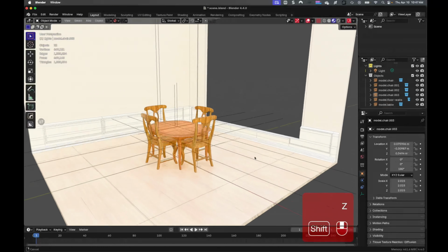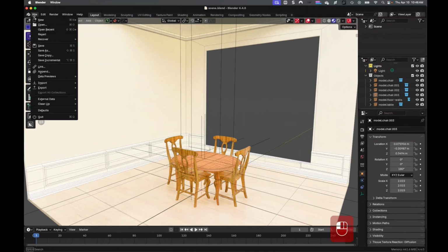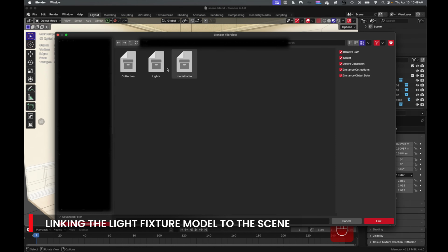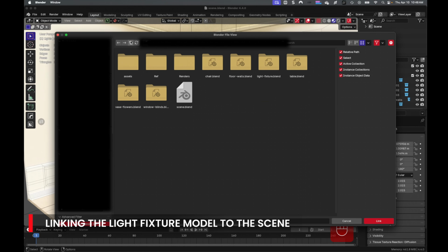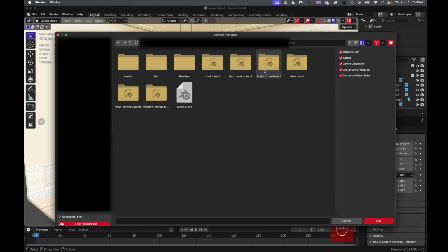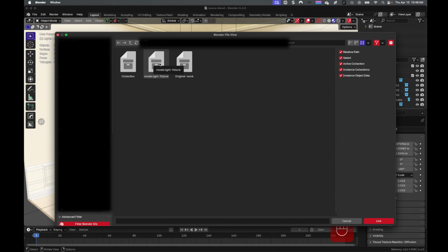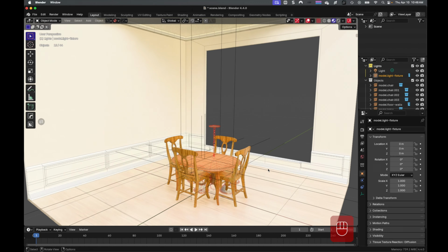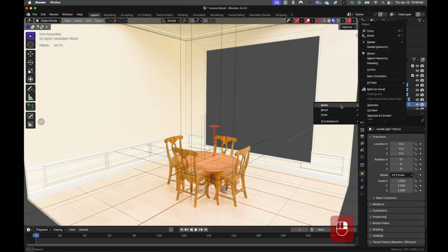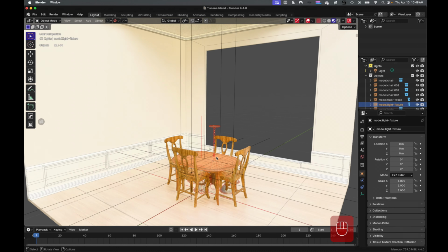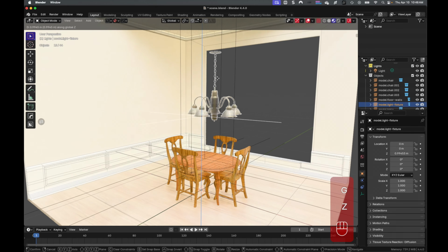All right, let's look at material preview here. This is looking better. That window hole looks pretty massive, but we'll deal with it, like I said, when we tweak it. Let's go in here and bring in the next model. I'm going into collections, and I want the light fixture. So there it is. And I need to move that in the outliner to the proper collection, which is my objects collection. And then I need to override the selection so I can move it up.